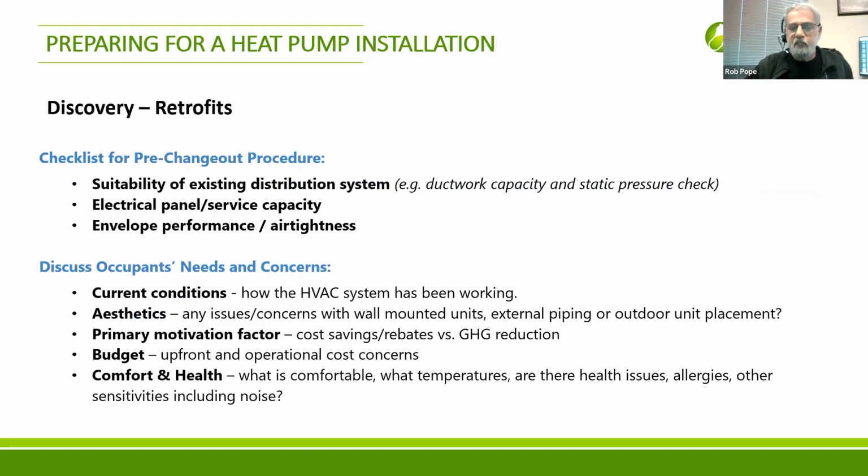In retrofit, it's not quite the same process because there's already a system there. So you're kind of stuck with what you can do to that system, or maybe you can't do anything to it. It's basically working with the system that's already there. What you want to do in that case is make sure that the system can deliver the airflow you need to put that heat pump in, right? Heat pumps are pretty finicky. You've got to have the right airflow and make sure the duct can do it.